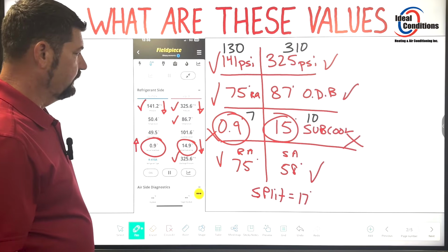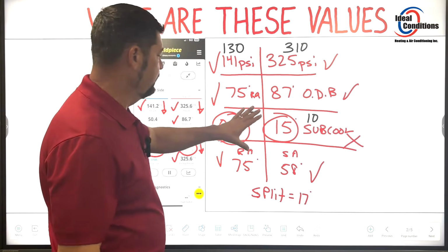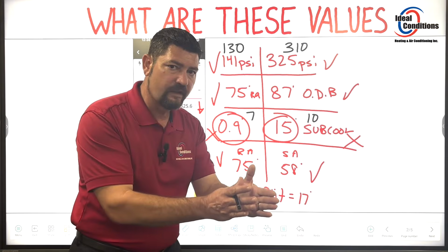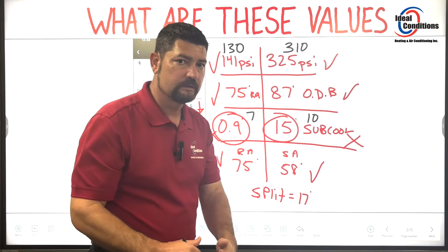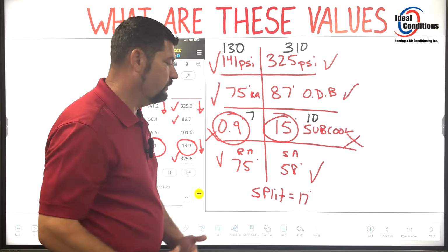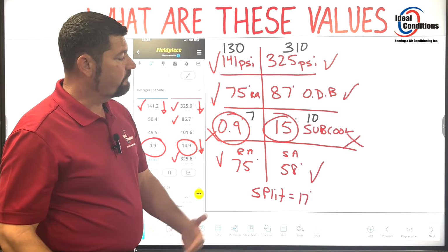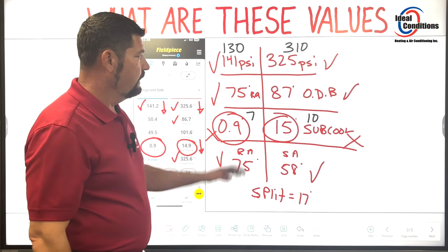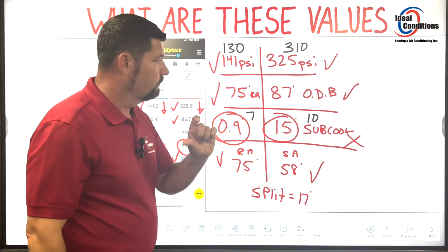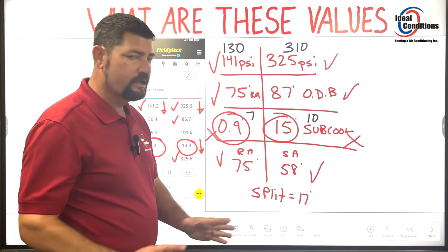Right? And if that was the case, just by taking a little bit of refrigerant out, not letting it out in a flower bed, but putting it in a recovery tank, you're a professional, right? You owe it to the industry, you owe it to your client. By removing a little bit of refrigerant out of that system, just a little bit, just out of my high side, I don't even need a recovery machine to do this.